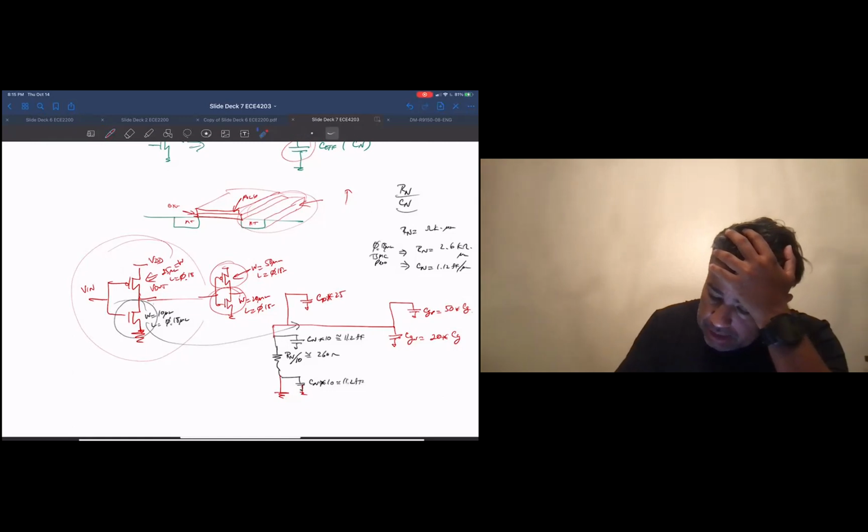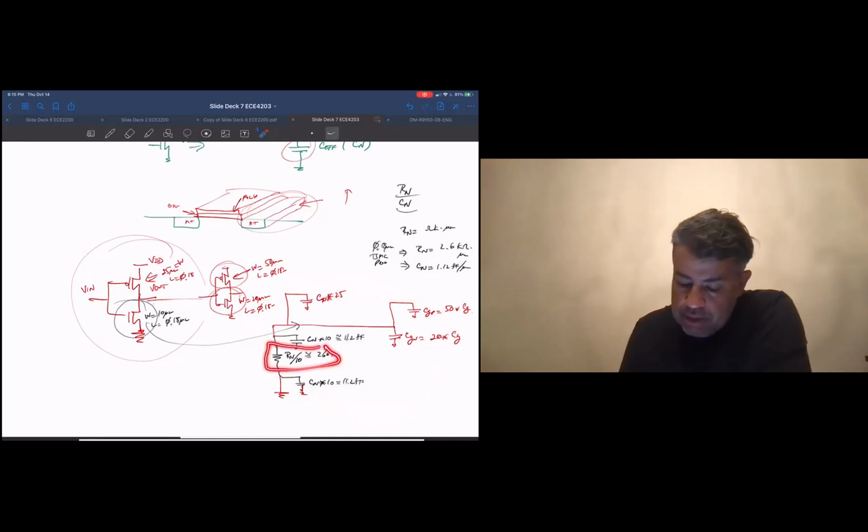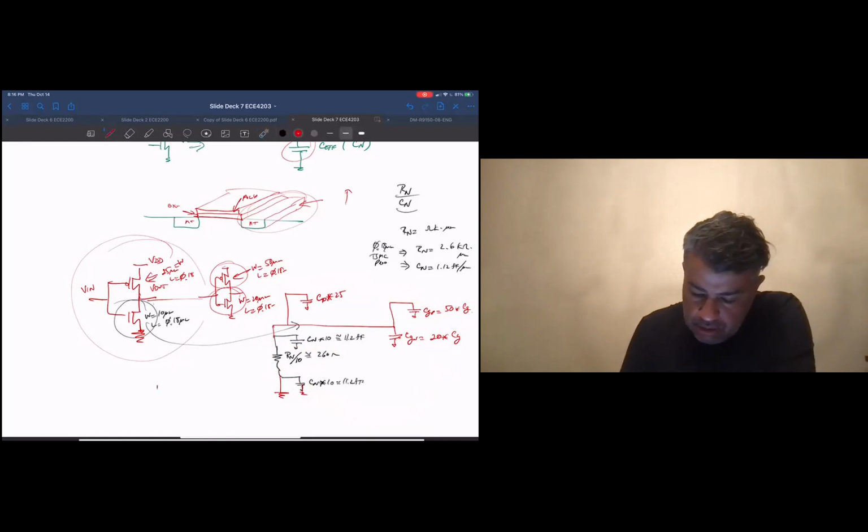So basically, I would end up with this RC network. In summary, I'll have a single resistance, just on the pull down. Like I said, I can get rid of this because it's connected on both ends to ground. So it'll be 260 ohms. Then I'm going to sum up all these capacitances because they're all in parallel.